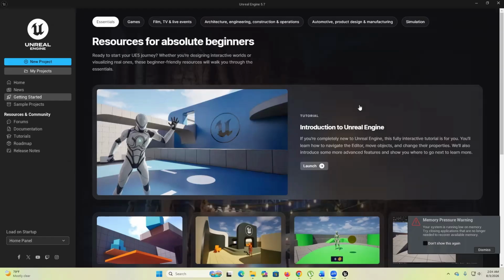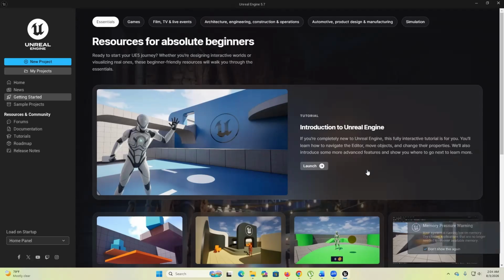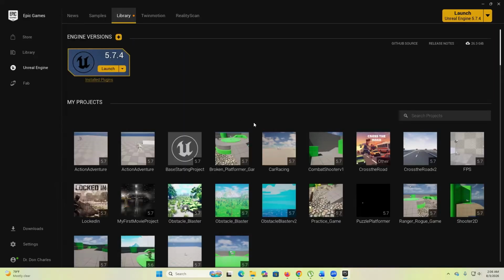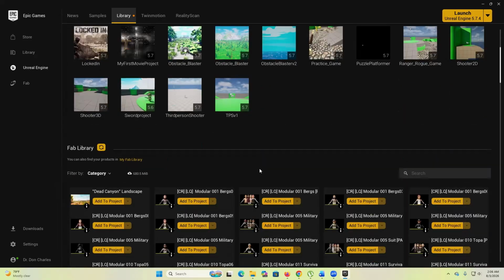Okay, so what I'm doing right now is looking for animations. I want to get the left and right animation. So what I'm going to do is use the Lyra starter project animation. So I need to create a new project with Lyra, and then try to export the animations. What I have just done is close off Unreal and go to Epic Games Launcher, where I have Unreal Engine selected here. Then I need to go to Library, and when I go to Library, I need to look for Lyra.